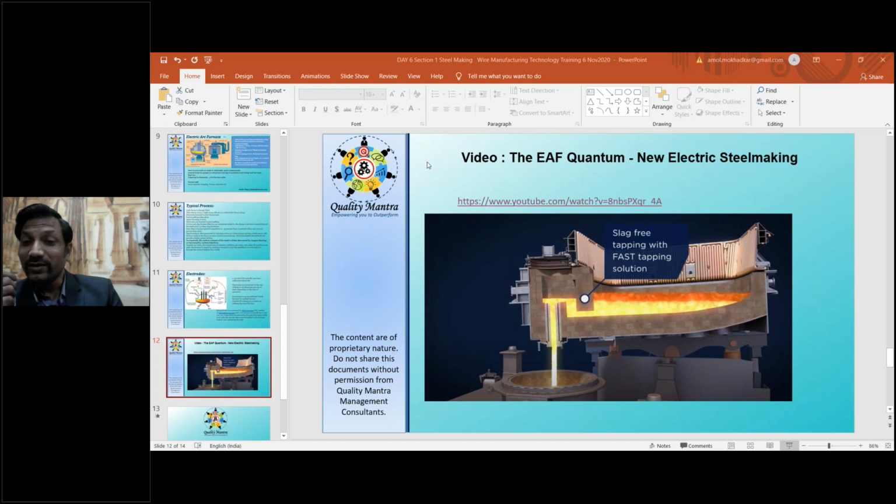So in this case, how they are avoiding the slag to go inside the tapping? When you are tapping, the slag is not getting removed. Okay, because slag is necessary for the reaction and for protecting the walls also. In the picture itself, you can easily see there is a water cooled lining. This is the water cooled lining. And this, they have lowered this one here. They have given one small separation. They lowered this separation so that when you tilt it, only the metal which is at the bottom is going to the tap, not the slag.